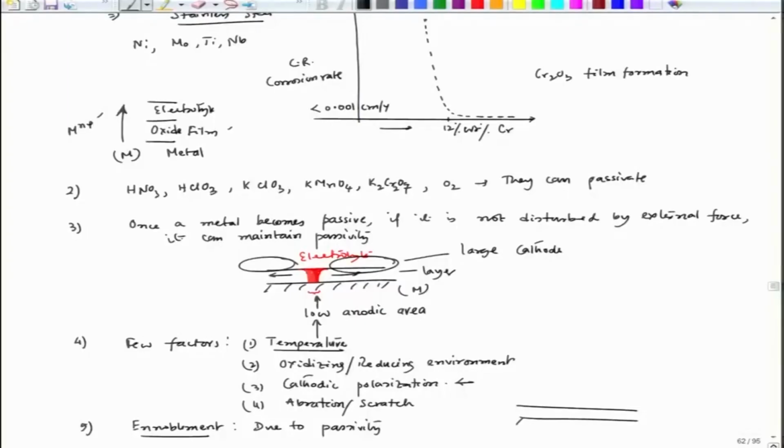But once the temperature reaches beyond around 60 to 70 degrees Celsius, zinc oxidizes and forms zinc oxide. Now, this is my iron layer and this is the zinc layer. Zinc remains as zinc if there is a small break. In that broken region, iron is exposed to the electrolyte.